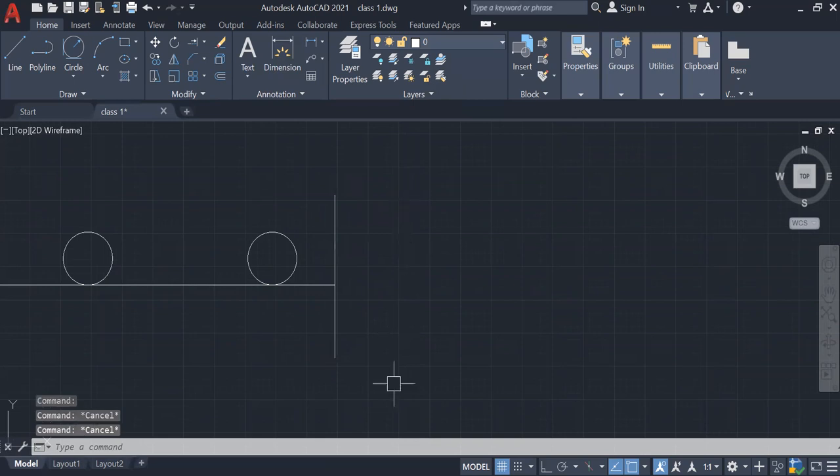I want to draw one more line over here at a distance of 500 meter. So how will I draw that one? I go to the line command, I draw this one, and I measure this one. Again, I copy that one or move that one, and I set it to the particular distance. If you are using the offset command, I have a line over here, and one more line I want here, one more parallel line or same object. This is a line object, one more same object I want here at a particular distance from here of 500.